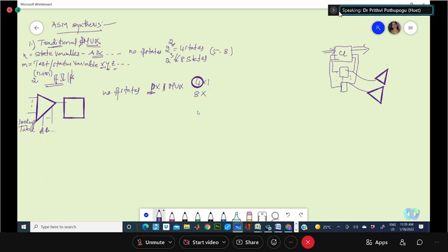Or you take an 8-to-1 mux, say. Here the number of selection lines is 3, so 3 state variables, and so on. And for 4-to-1, the number of selection lines is 2, that means your state variables will be 2. That means, see here, however many state variables you have, that many D flip-flops and that many muxes will be used, because a pair of mux and D flip-flop will be used in this path.